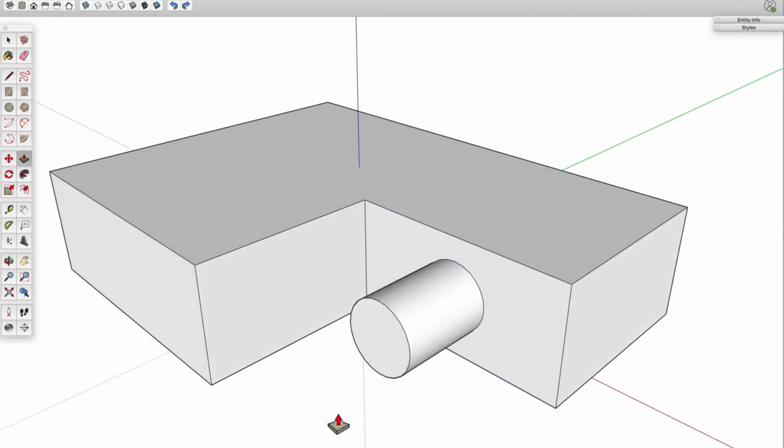Okay, now let's say that we want to push-pull this all the way back so that it's flat again on the surface it came from. So with the push-pull tool, click once, let go of your mouse, and then begin moving your mouse so you're push-pulling it back. And again, we don't want to eyeball things here. So even if you think you've got it real close, you're guaranteed to be some tiny, tiny fraction off if you try to eyeball it here.